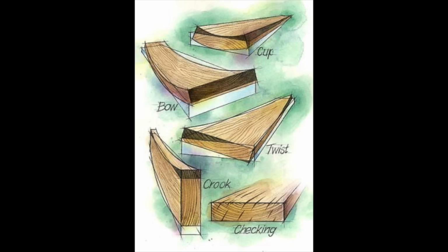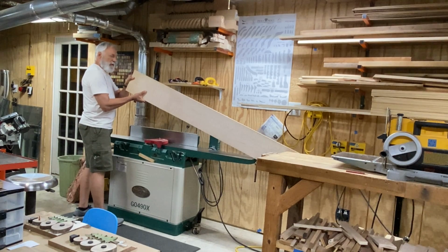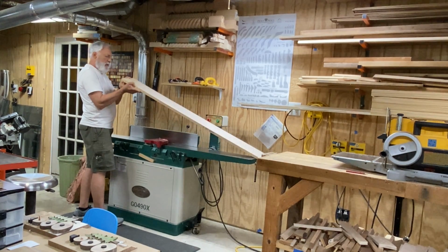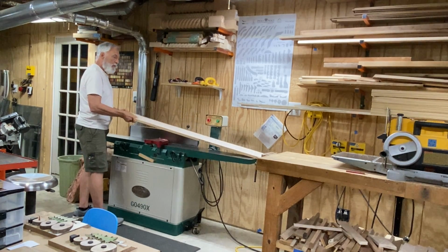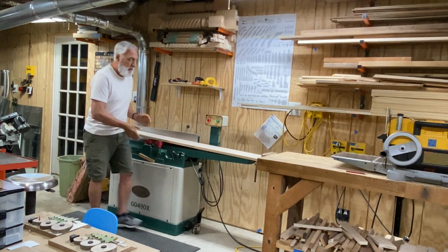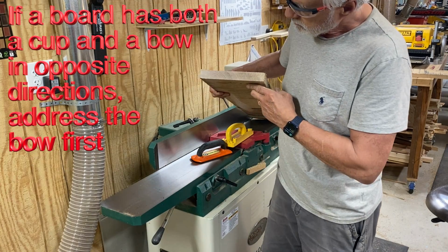Yay! Once your jointer is set up and you have your first board in hand, you'll realize one of these types of warp will be predominant. Each board will tell its story when you look down the board, which will tell you the best way to mill it properly. If you have a board with multiple issues, or if one of them is extreme, just don't buy it in the first place. Or if you did buy it, use it only for small projects.